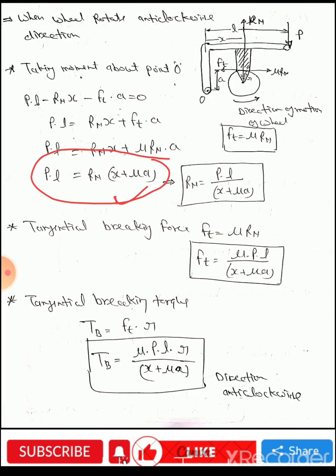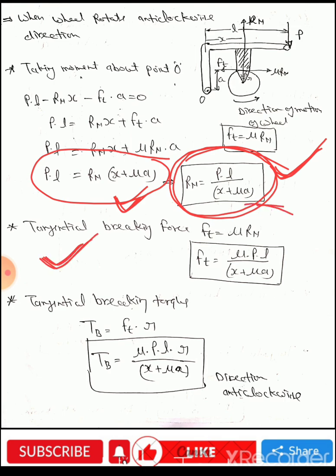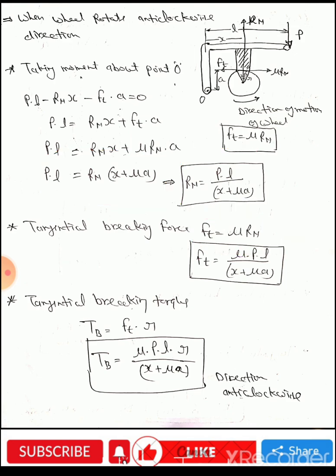From this equation, we can obtain the value of Rn as PL upon x plus mu A. This is the normal reaction value. Now we can obtain the value of tangential braking force. Ft is the tangential braking force, and this is equal to mu Rn.